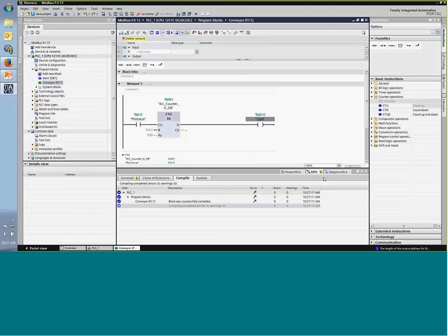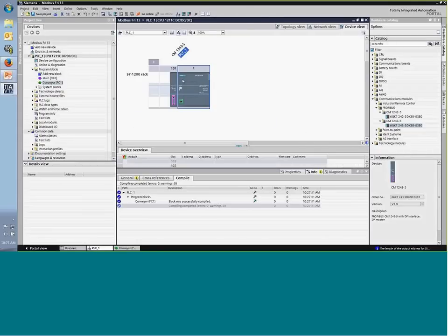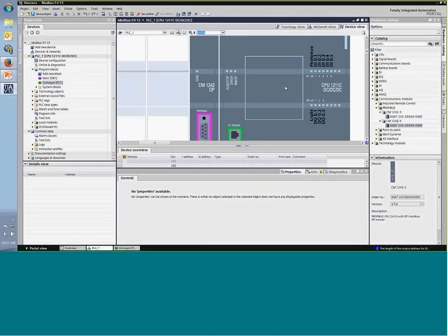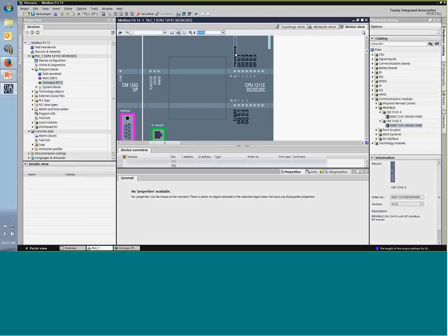So if you notice, this area now changed and it came back with a compile area and gave us 001. There's one more feature. If we go back to our PLC in this picture and double click on it, and let's say I zoom, you can view all the IOs right here. So the first input is now described as photo eye and light. So let's bring up some inputs and outputs, and I don't know what I used in my code and what I left out. I can simply go back here and look, okay, my inputs are empty and these outputs are empty, and this is where my light and the photo eye are. So it's pretty cool.